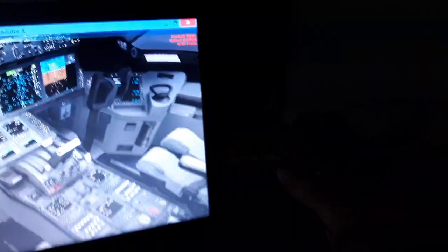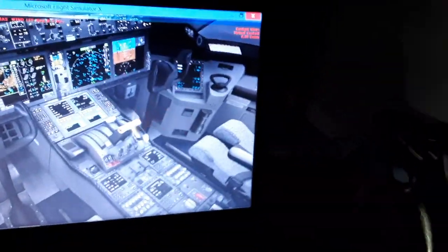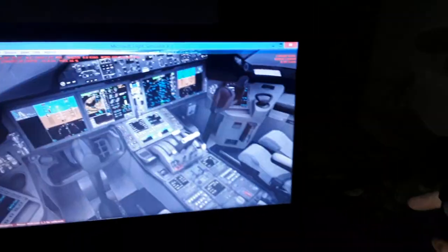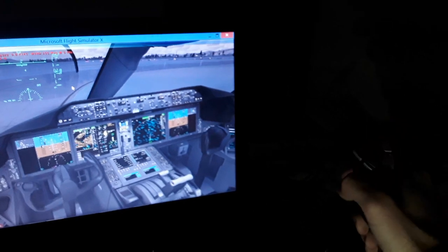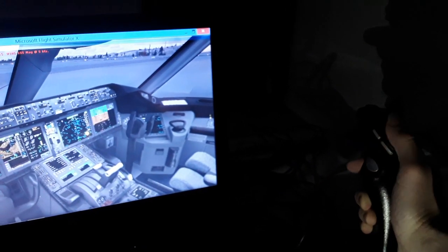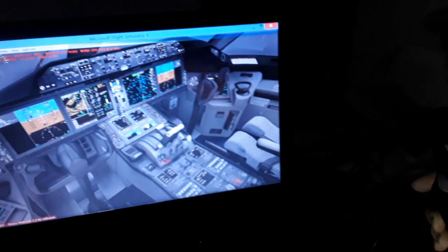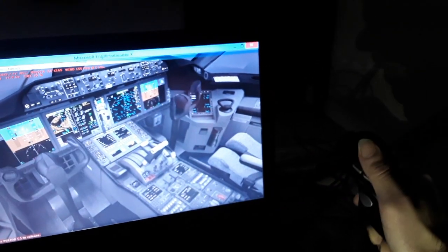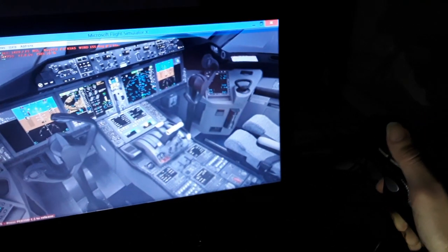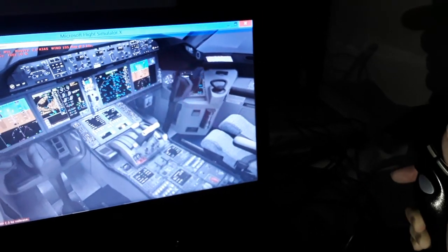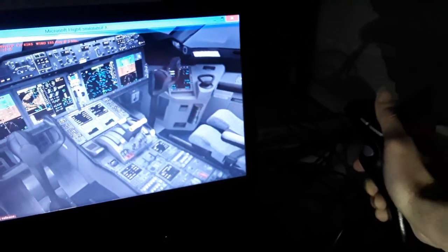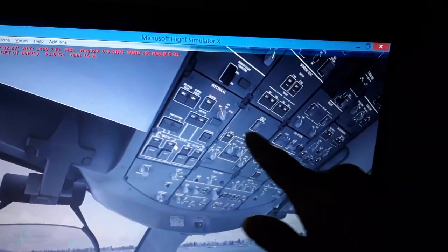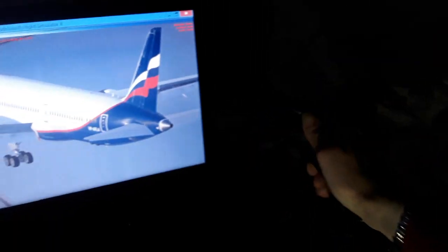When you move the flight controls, the yoke, the others, the spoilers in flight, you give a command to the flight control computers. We would change the position of the aircraft. Flight controls command the attitude of the aircraft in flight in terms maybe of G acceleration, like in the Airbus aircraft, for climb, descent, or making turns. So you have also hydraulics over here, which move the flight controls. You see the flight controls move when we move the hydraulics.